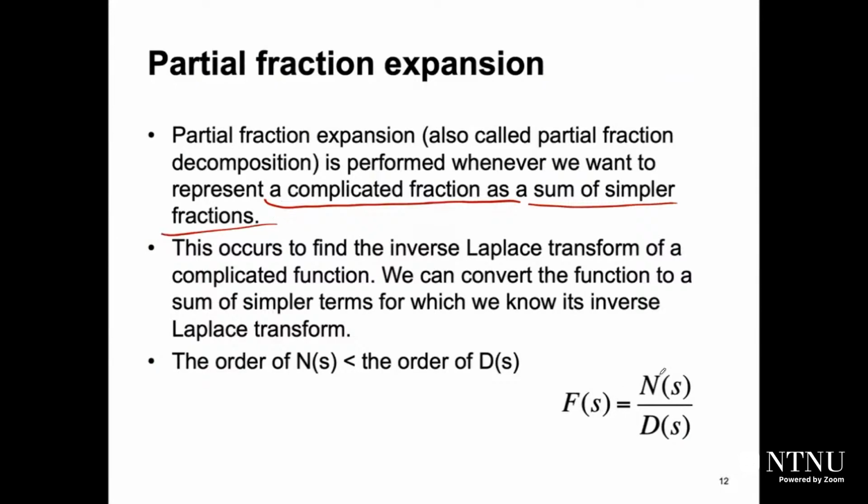So we have a transfer function, and this transfer function is a numerator divided by the denominator, and it's a complex fraction, and we need to simplify it as a sum of simpler fractions. And when it is a sum of simpler fractions, it's easy to go to the Laplace transform table and apply the inverse Laplace transform to get the solution of your differential equation. So if you have a complex differential equation, you just need to put it in the frequency domain by applying Laplace transform, and after that you apply a partial fraction expansion to convert it into a sum of simpler fractions. Then apply inverse Laplace transform to get your solution as we did here.